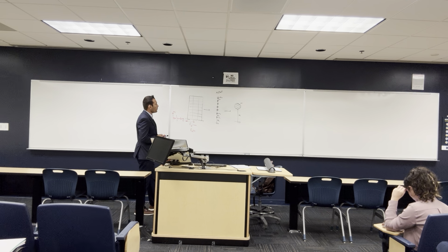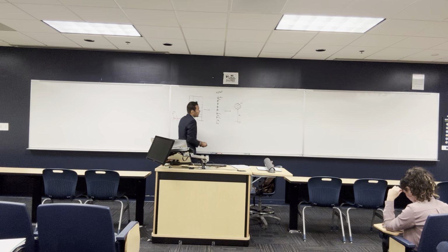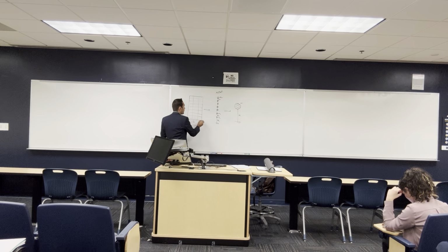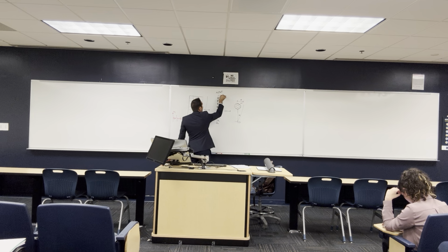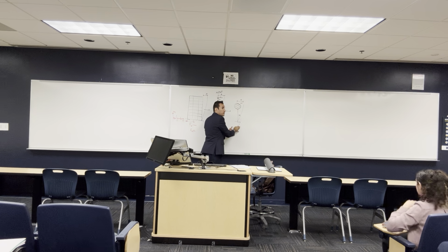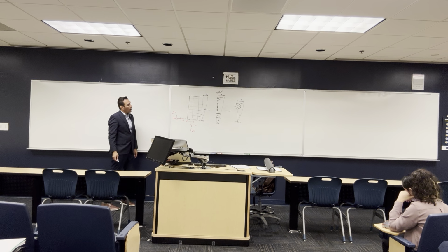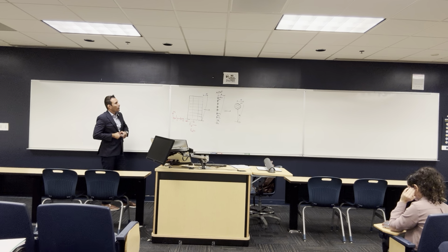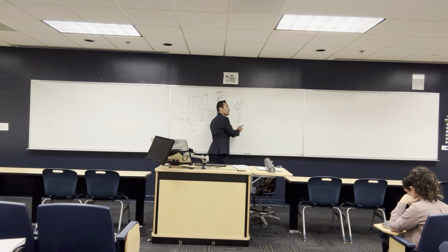Knowing all these simplifications, I told you there's one common thing between these buildings. Because they are supposed to be the same, if this building gets exposed to this earthquake, it's going to give you a delta like this, and this one a delta like this, and this one a delta like this. And all of them should give you the same delta, because it is the same stiffness, same mass, just summed in a way that gives a total mass and a total stiffness. All right, so how can we get delta? Either from here, here, or here. The thing is, this is very easy to solve.